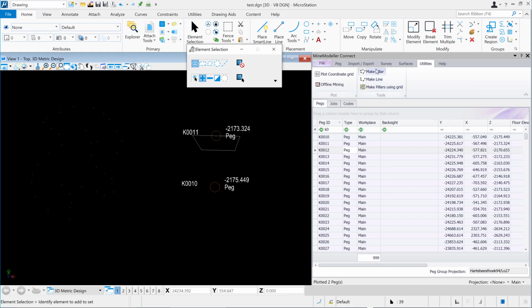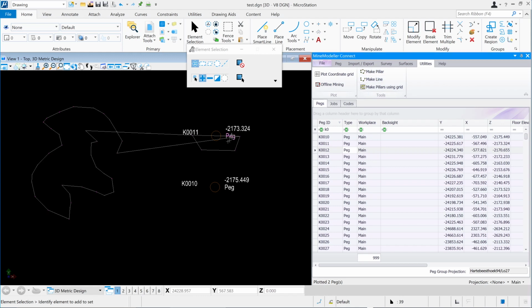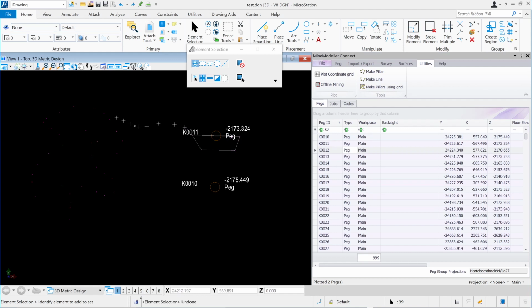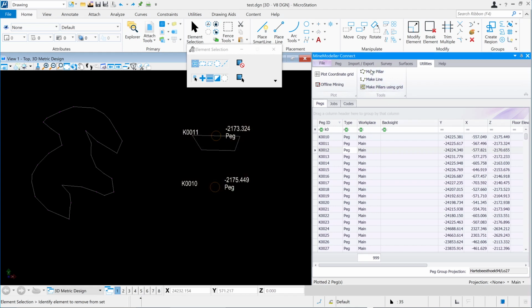If I say make pillar from those, you will see that it pretty faithfully to what I did, except, oops, I selected a point over there. Let me just undo that and make sure I remove any point from this side here. And if I say make pillar, it will do a perfect following exactly as I did it to make a pillar from those points. It's another little feature that we have in Microstation. Okay, so what we can now look at here is that was the offsetting, the drawing a pillar.